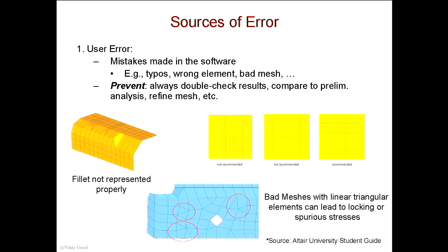Other problems I have seen include boundary condition errors and loads not applied properly. You thought you included all the loads, but you didn't. So always check your results, compare, refine your mesh, and do a lot of different checks.